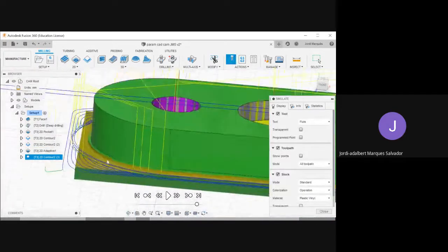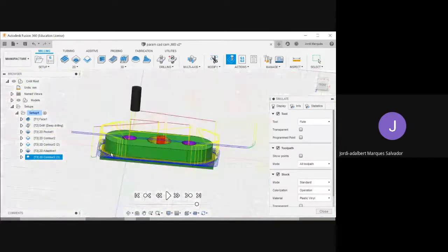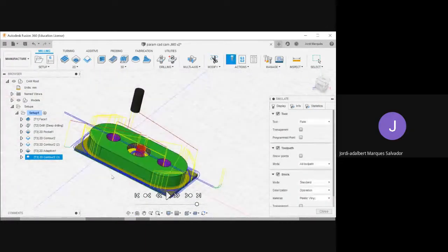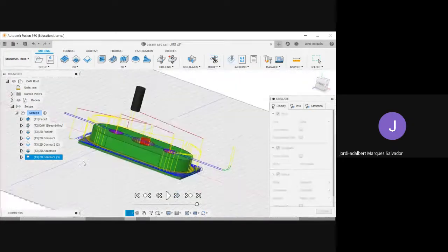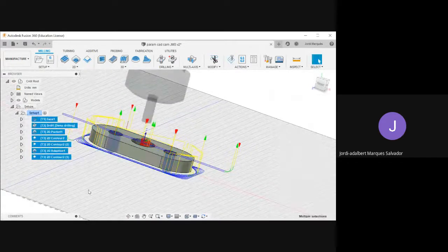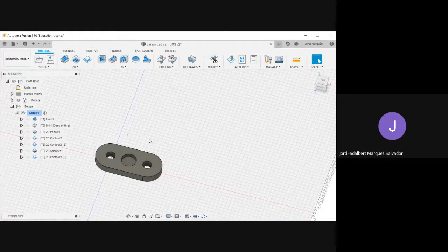Nearly finished, okay? You can see here the small gap. Here you can see the profile of the part, this stock that we need to remove. So in the next session, this is the most important thing, we'll be seeing how to generate another setup with the same part in order to generate the facing operation that will take out all this material. So just to finish, here we have this nice program of this part, and now comes our client says, hey, the part is 2 millimeters longer because whatever.